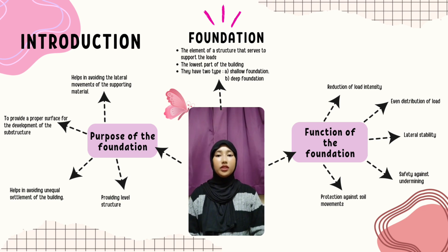A tall building like a skyscraper, or a building constructed on very weak soil, requires a deep foundation. If the constructed building has a plan to extend vertically in future, then a deep foundation must be suggested.